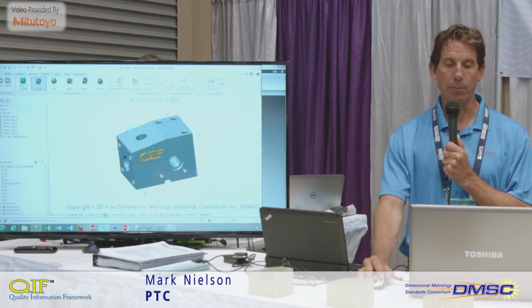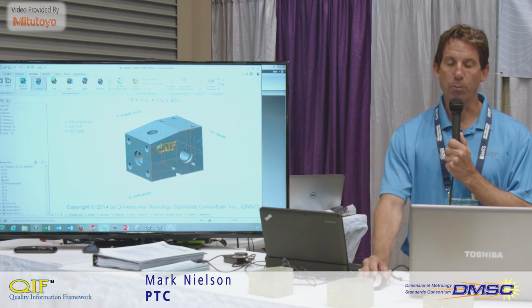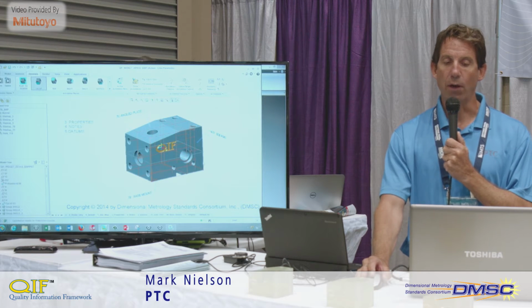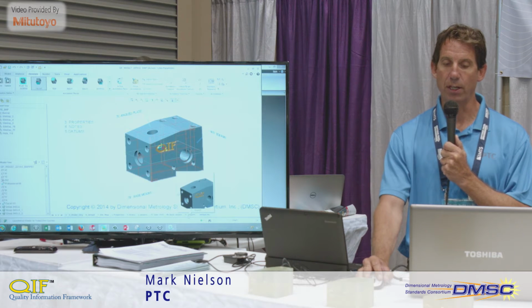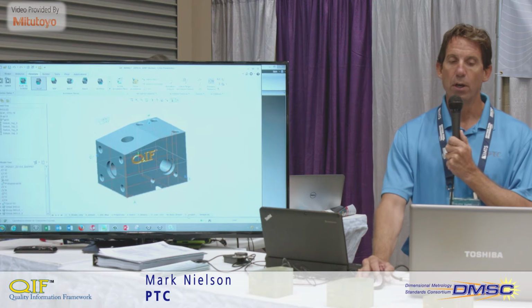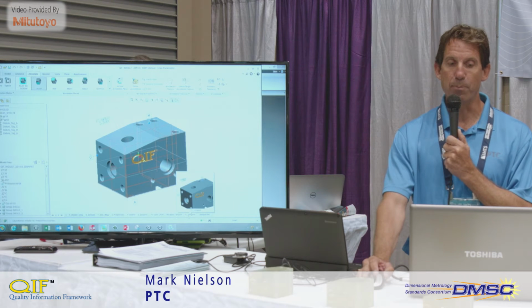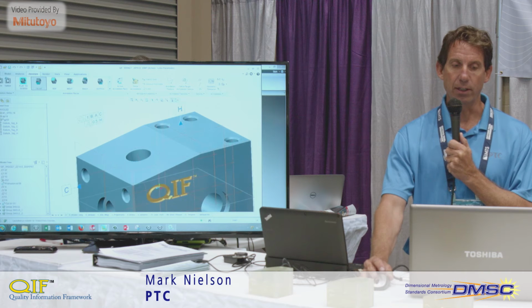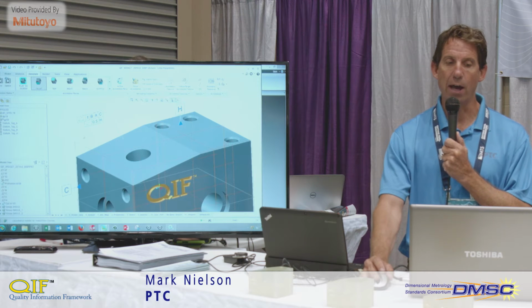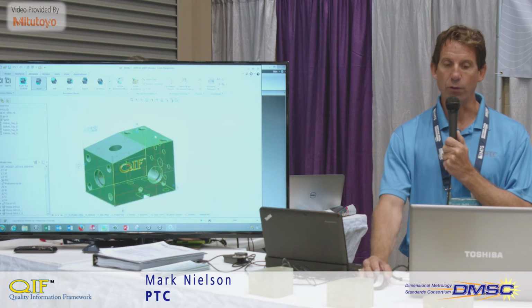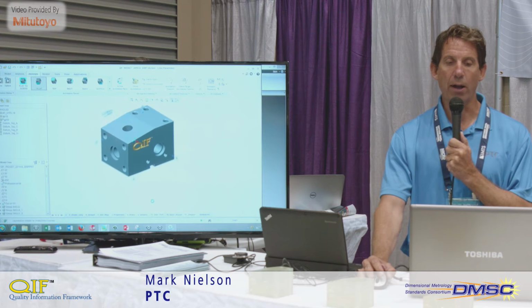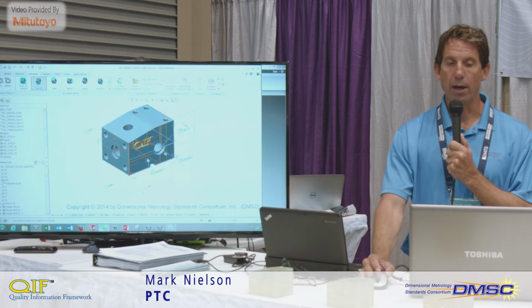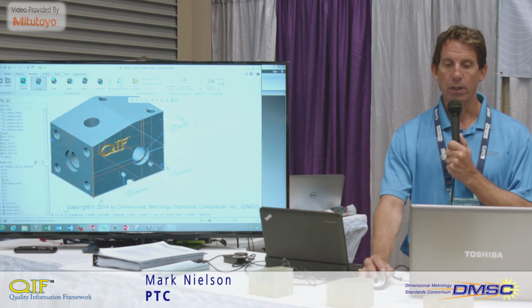If we go back to the site map, you'll see the model is broken up into different areas that are annotated. So if you want to see the angled plate, you would go to 7C here, and it will show you all the dimensions, or at least the non-standard dimensions for that plate. And you'll have things like the profile callout, the angularity, the reference frame that are associated to that. And that's the typical modeling paradigm for model-based definition.